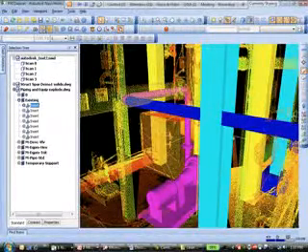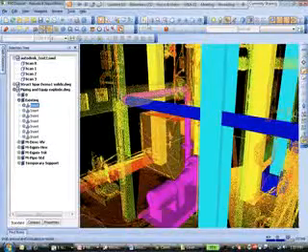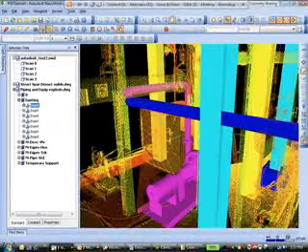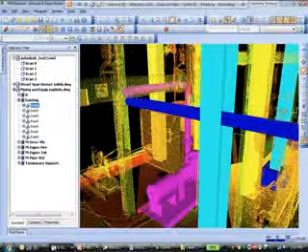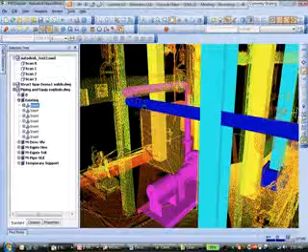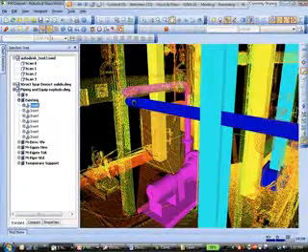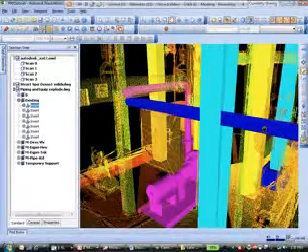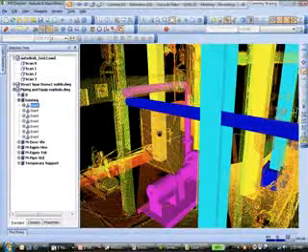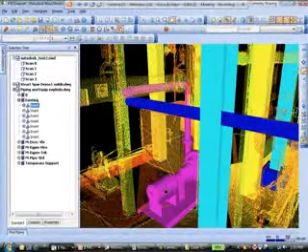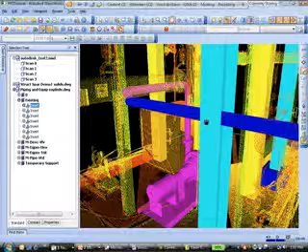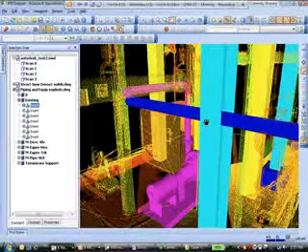We could do some of that in Navisworks, and we can say, let's just hold this pipe here, just to verify that this would work. And basically, I've just dropped it down a couple inches. I could then rerun the clash test, and now if that clash is gone, then I could go back to the design model and say, let's make this change. I need to move this down. But let's say in doing so, I've treated that clash, but now I've caused another one farther over. So it gives you the ability to do some what-if scenarios. But ultimately, it's not a design tool. You would go back to AutoCAD, MicroStation, Revit, whatever application created these initial shapes, and then re-import that back into Navisworks and run it through the clash test again.